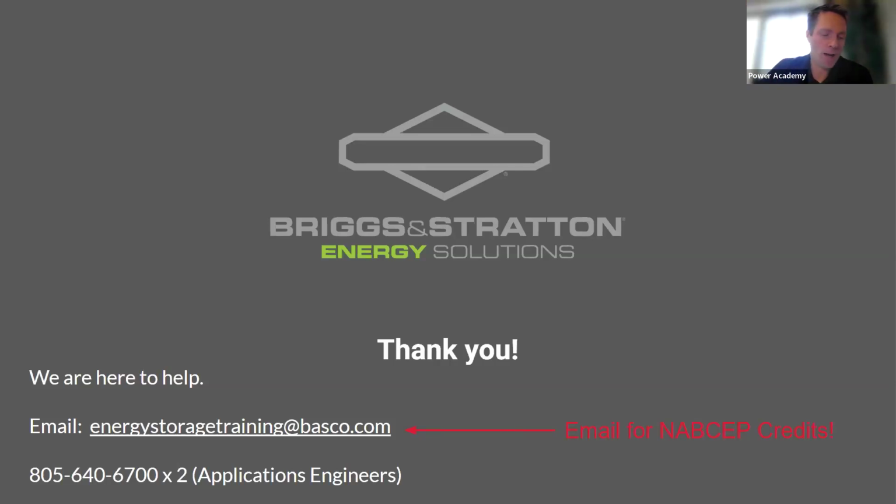Well, I'll start off by telling him why we're limited to the number of modules that we are with 6 stacks. We are limited to 18 modules in our systems based on communication. There's a lot of communication happening from battery modules to battery controllers to each other, and then those aggregated controllers into the inverter. So the coding for our batteries, we limited it. That could be expanded in the future.